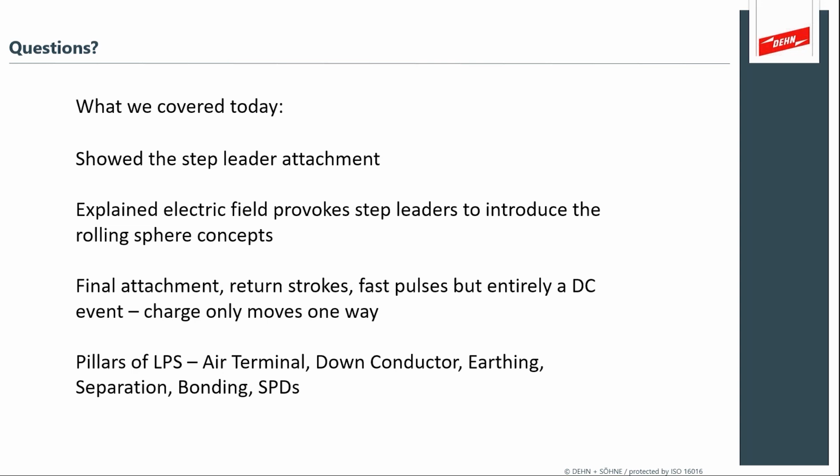I think this comes up where people are trying to create a lightning protection system that can address lightning currents smaller than 3 kA. So something like a 10-meter radius rolling sphere, or even if they've done their research and they see that an area normally gets lightning strikes more than 16 kA, they try and develop a rolling sphere that's bigger than the general 60 meter radius rolling sphere for LPL4. But it's like you say, Mark, and I agree that the standard just doesn't give guidelines, and equipment ratings have not really been done according to those things.